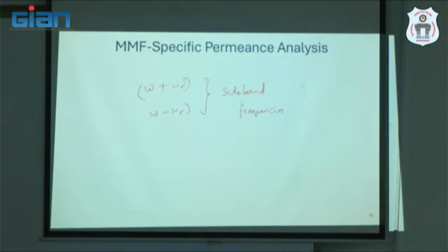So the moral or the summary of this long exercise is, if we have to carry out current signature analysis to diagnose mixed eccentricity, we have to do the current spectrum or frequency spectrum and look around the 50 Hz fundamental frequency. We have to look for sideband components. Depending upon the rotor speed, it will be offset. So that is how you can estimate.